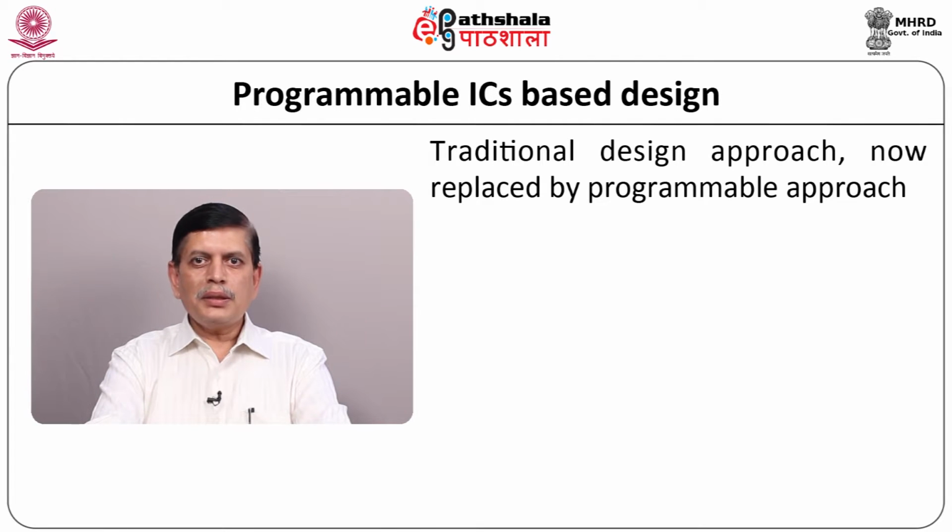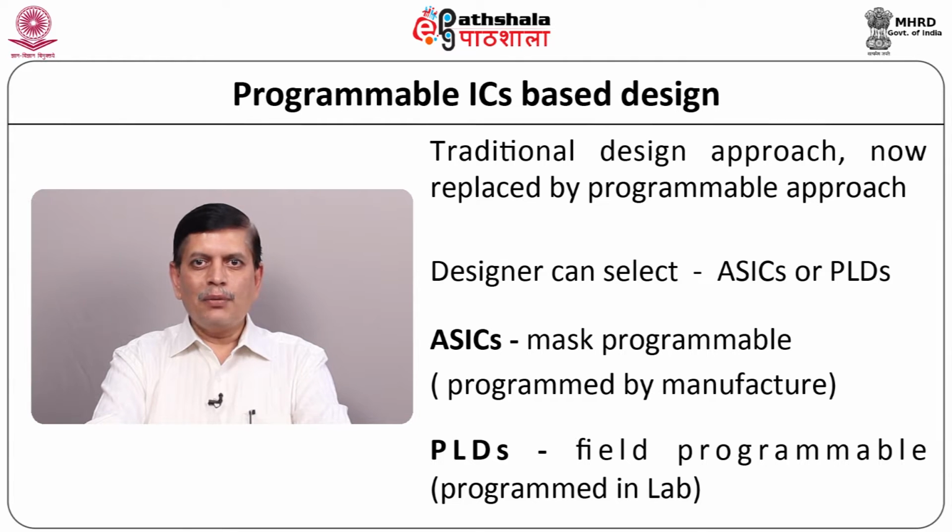The traditional approach is nowadays getting replaced by the programmable approach. The programmable approach has two options. The first one is programmable logic devices, the other is application specific ICs. Programmable logic devices are field programmable, where the user can program these ICs, whereas application specific ICs are mask programmable, which are normally programmed by the manufacturer.